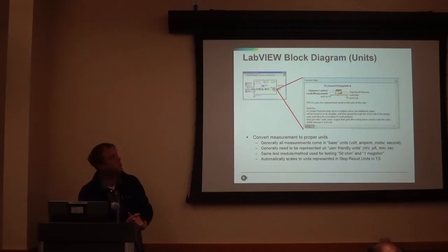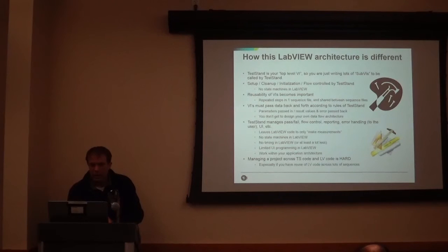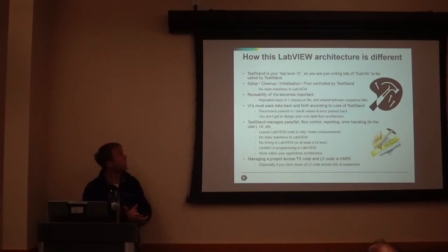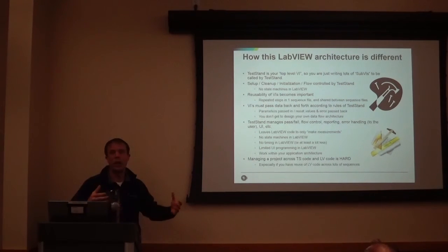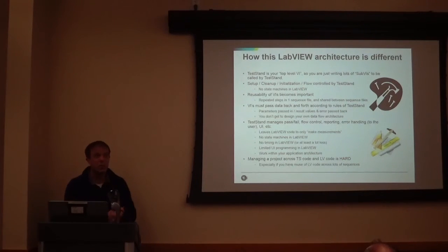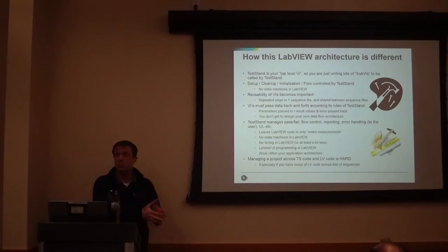Unit scaling, we talked about that a little bit there, and where this really comes into is TestStand. The TestStand sequence file user interface is my top level VI. That is what's running it. I don't have a parent LabVIEW project application that's running for that. All of my setup and cleanup and initialization stuff that you would have to do for a full-on LabVIEW test executive is all handled by TestStand, that it controls setup stuff, cleanup stuff, through all that.